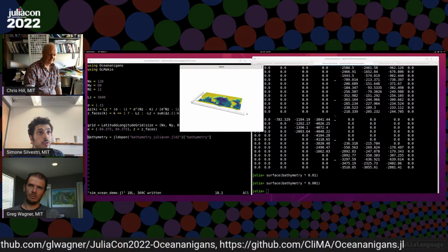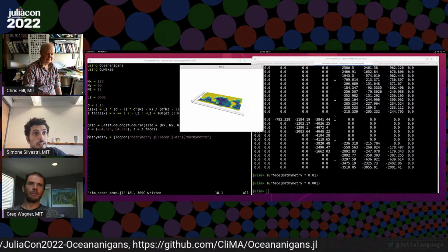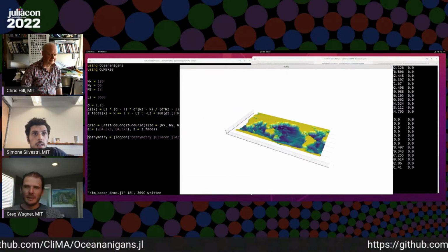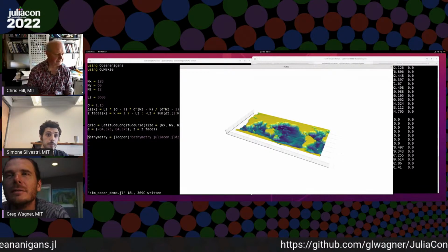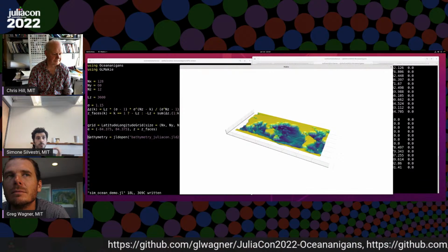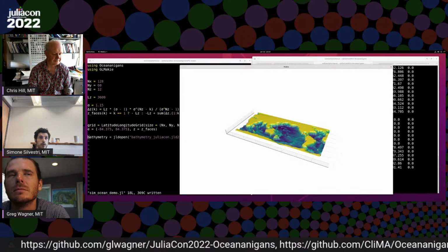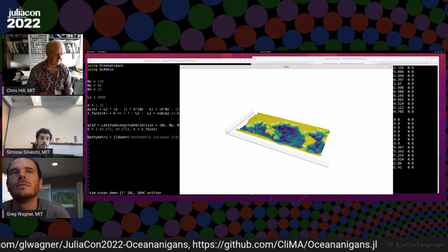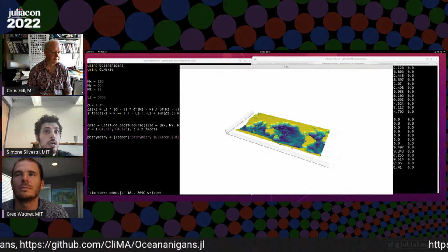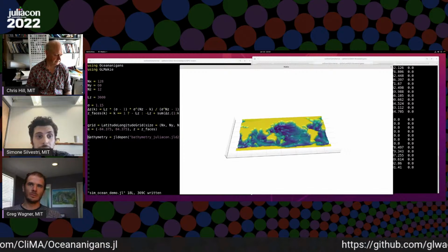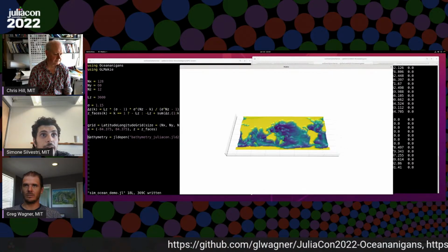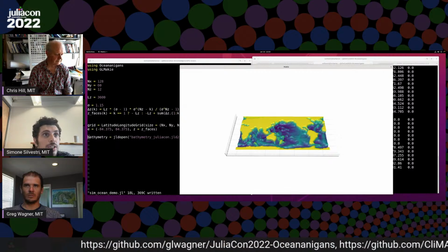So if we overlay this array to our grid, the grid will know that whatever is above it will be part of the fluid domain, and whatever is below it will actually be part of a continent or will be covered by terrain. So everything will be masked to 0 and not be calculated. As you can see, this bathymetry is kind of coarse, but it has everything that we need. So it has Africa here, America, some bottom here, some ridges.